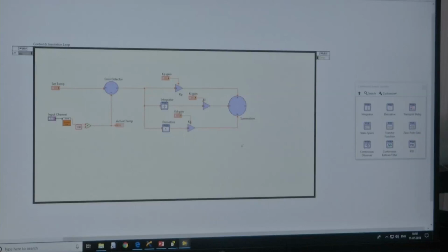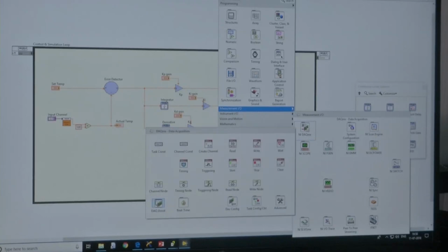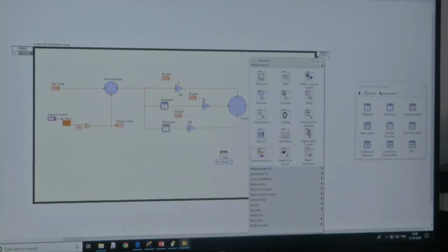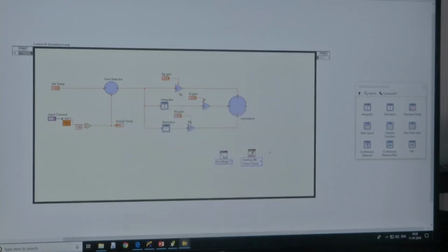Again, we have to make use of data acquisition. In a data acquisition unit, we have to use generate signals. How do we do that? For that, I am going to measurement and instrument. Here I will be using create channel, but previously we used analog input read, now we will be using write, that is it. But now it should be analog output, not the input, should be voltage, and single channel, single sample and DBL form.